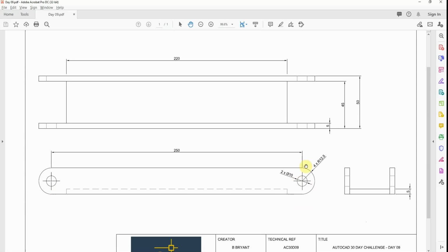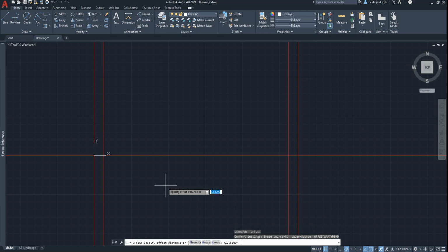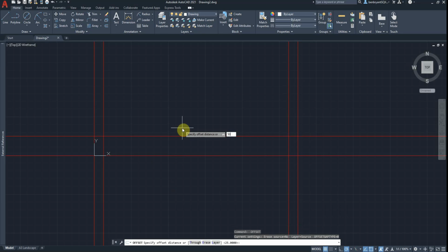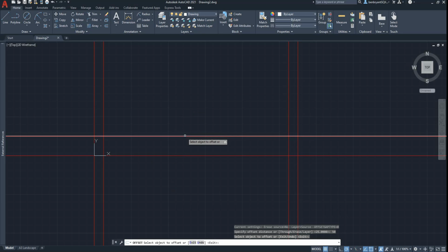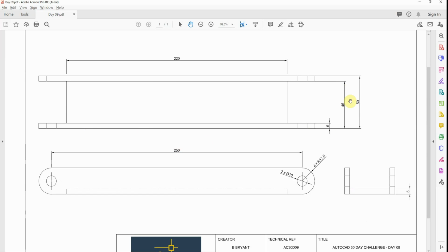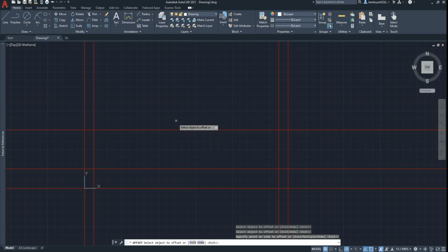So next up, I know it's obviously then it's going to be 25 high, so obviously you've got 12.5 times 2, which is 25, so then we're going to put the offset of 25 in, like so. Offset of 50, just space it on my page. This is going to be then the bottom of my top component, and my top component then is a further 50 with 5mm either side. So 50 again, coming up, and then offset 5 down, and then 5 up. That's going to give us the 45 in that central pod.